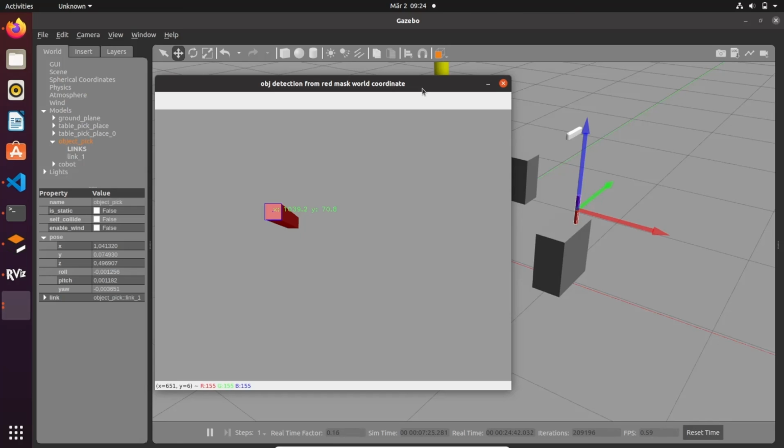So before I leave you, I want to make a disclaimer on this application. We have used a depth camera to get an image, and we have created a color mask. Based on that, and based on OpenCV tools, we are getting the conversion between pixels and millimeters based on the mask that we have created. So we have measured this object somehow,